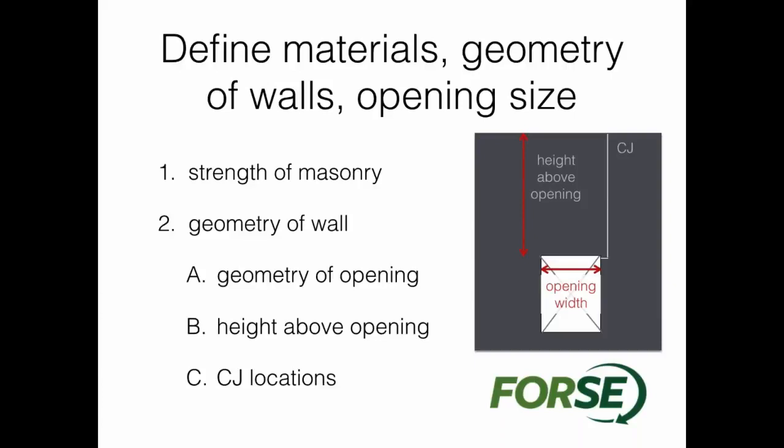First of all, strength of masonry. Again, we're going to just recap that really quickly. It's really important. I mean, for lintel design, depth of that lintel, amount of reinforcement at the lintel, using the right strength is certainly very important. With finite element analysis, I talk about this all the time. You can't be conservative by using low strength values within this finite element analysis. You have to be accurate. It's not conservative to just use 1500, to just use these low values. Be accurate with your modeling. So we'll talk about that.